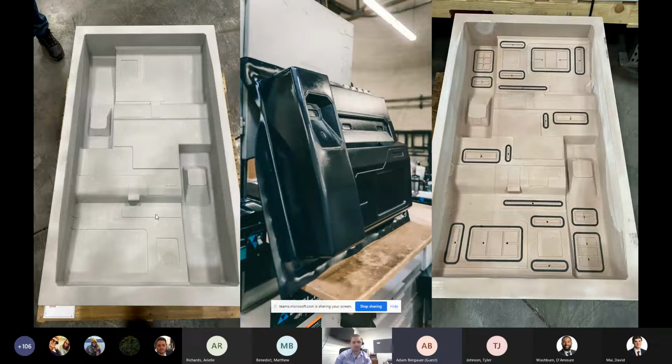So that sheet is then laid into a clamp frame, and then the clamp frames are sent into an oven, and the sheet is heated up evenly. Kydex usually forms around 380 degrees, so you have to heat it up very evenly all the way around the sheet. This sheet, I believe, is 47 by 29, 47 inches long by 29, so it's nothing too big.